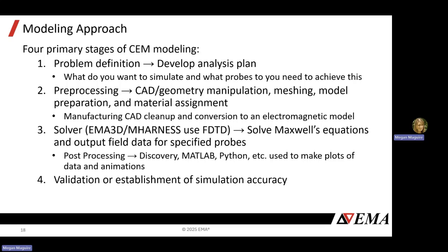For EMA3D and M harness, you use an FDTD mesh and solver, in this case solving Maxwell's equations, and then outputting field data or current data based on the probes you select. That data can then be processed in Discovery, or for more advanced methods, you may choose to use MATLAB or Python to make plots and animations. And then lastly, depending on where you are in the process for your program, you may be at the point where you want to do validation or establish simulation accuracy or margins.